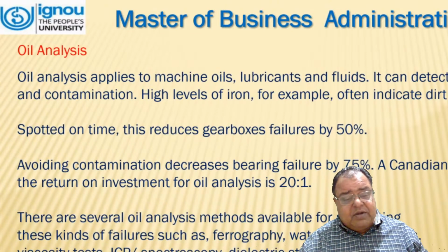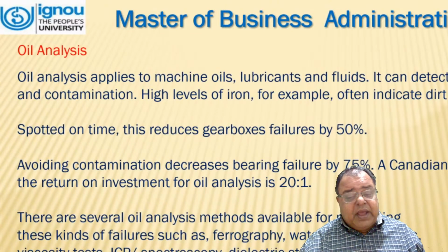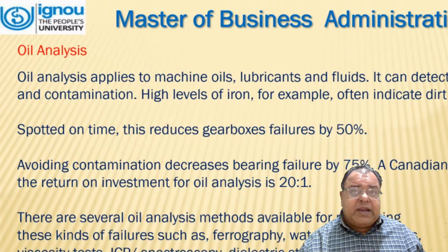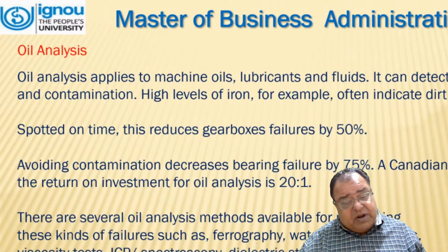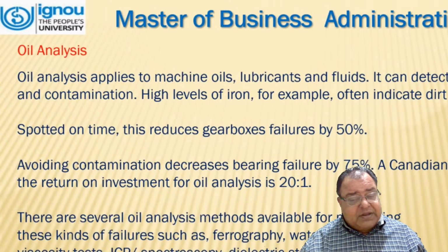There are several oil analysis methods available for preventing these kinds of failure, such as ferrography, water presence test, viscosity test, ICP or spectrography, dielectric strength test, and microbial analysis, etc.